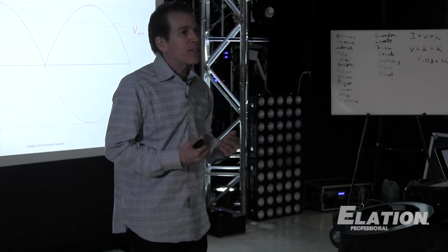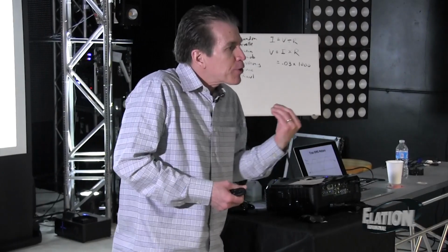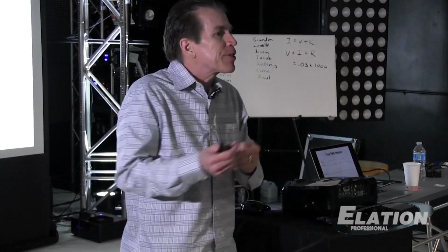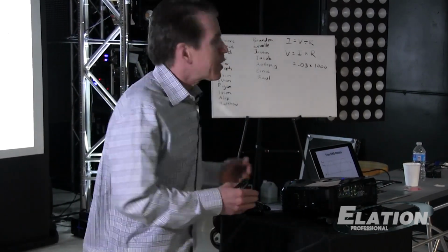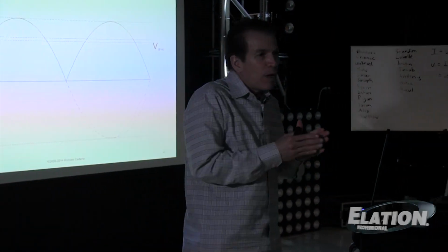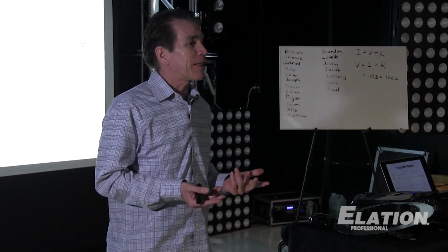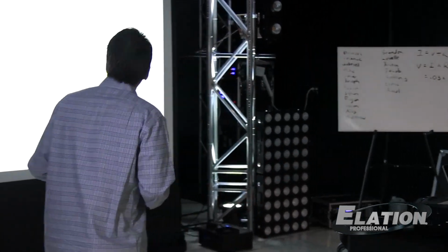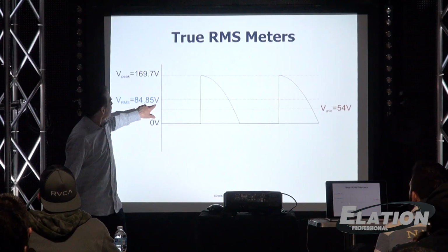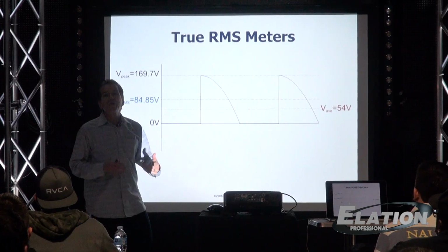But in our business, a lot of times we plug in gear like this projector that draws current in pulses or changes the sine wave in some way. So instead of the current being a sine wave, maybe it's current pulses or DC or something like that. And when that happens, the relationship between the average value and the RMS value changes, it grows. So that little multiplier we had before no longer works the same. So you start getting reading errors.